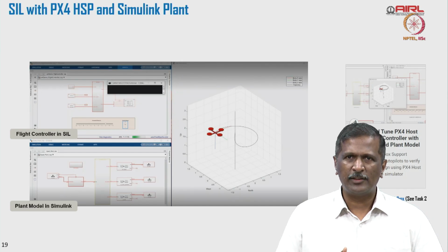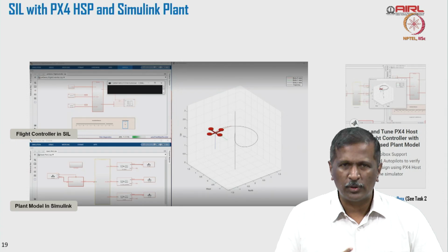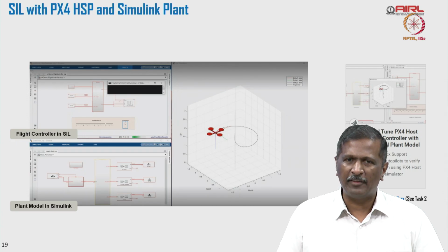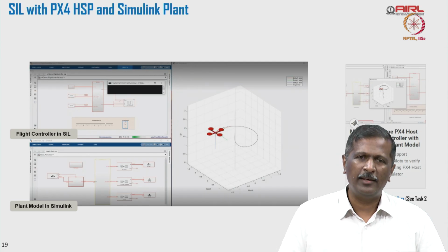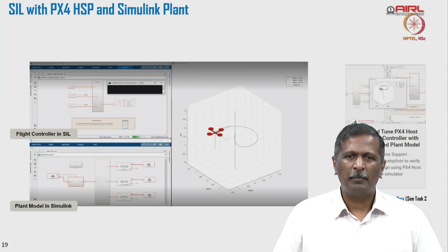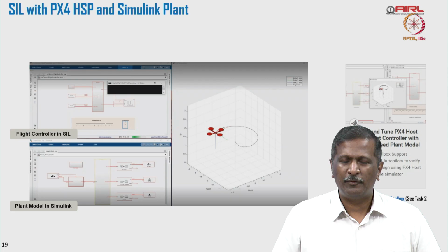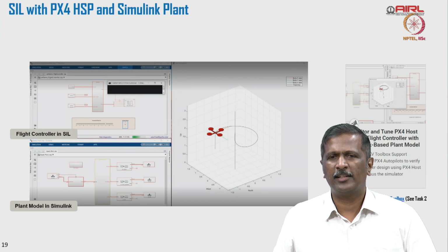Let's say you are passing through a constrained environment, cluttered environment, and already your positional error itself is plus or minus 2 meters, and this 0.5 meter error on tracking means you may be on top of the building, right, then between the building. So we need to figure out where that trajectory error is, for what kind of mission it is acceptable, for what mission it's not acceptable.